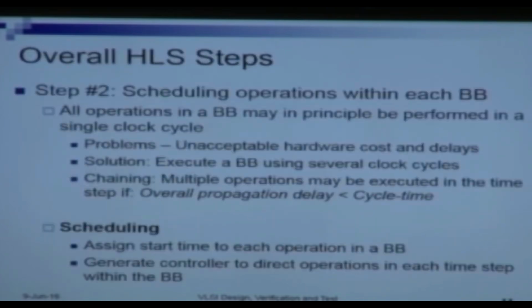However, if we have many operations within a single clock step, the problem is that it will lead to unacceptable hardware cost and delays. Why hardware cost? Let us say we have four comparison operations within a basic block. Because it is in a single clock step, I cannot reuse the comparison operator at different clock steps.